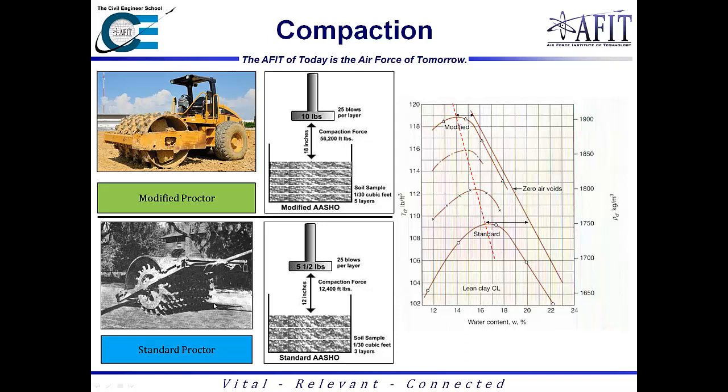However, as we started getting better and better equipment, the standard Proctor turned out to be ineffective for specifying compaction, because more and more they would have compaction tests that would come back as 105% or 110%, which doesn't make any sense.